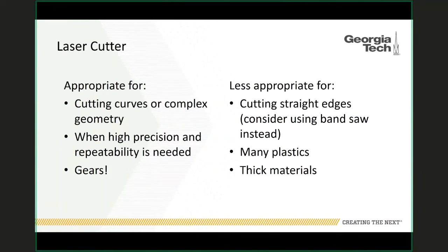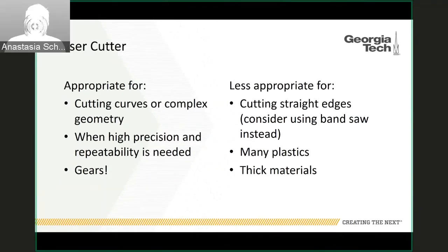The laser cutter is most appropriate if you're cutting curves or very complex geometry. If you need very high precision and repeatability, so if you're trying to put holes for screws or bolts in a particular place, it's great for that. It's also excellent for gears in this class. It is less appropriate if you're just cutting a straight edge.